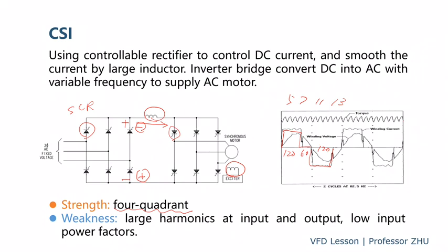And on the opposite side, the waveform is also not good. So this current will produce extra heating in the motor. And the torque pulsation will generate a resonance problem on the mechanical equipment.